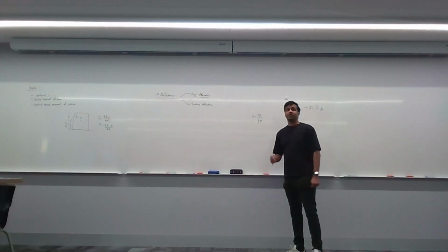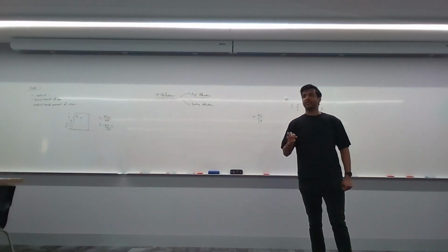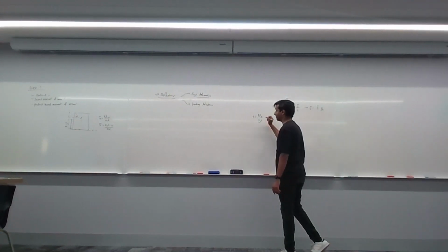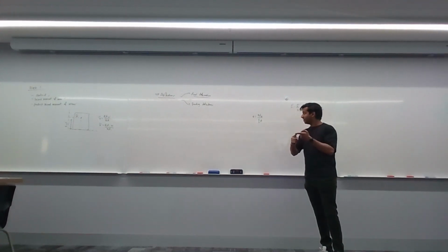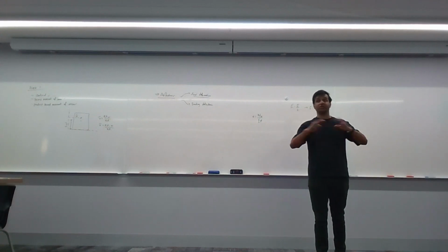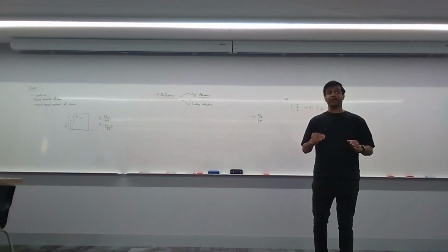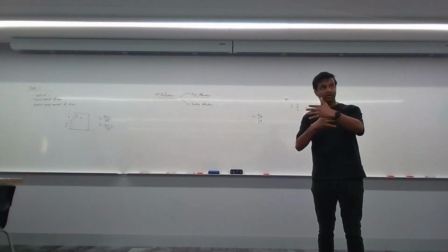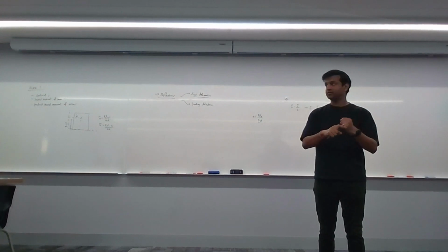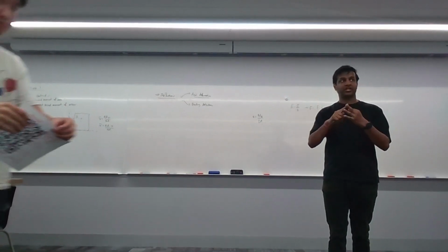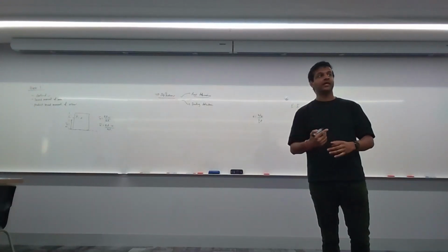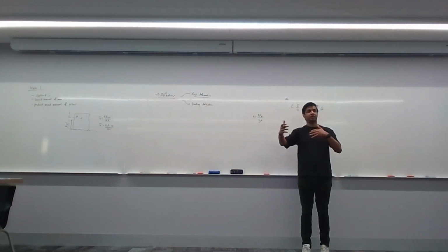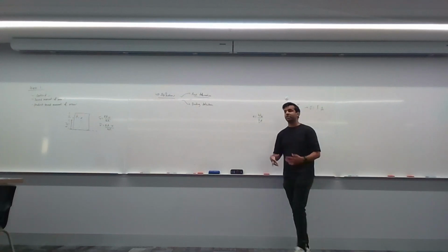Okay? Now, this formula only works if over a given distance L, N, E, and A are constant. You must remember that. This formula only works if over a given distance L, the force N, elastic modulus E, cross-section area A are constant. If any of these values change over your length, you have to integrate it. Okay? So I'll give you an example.